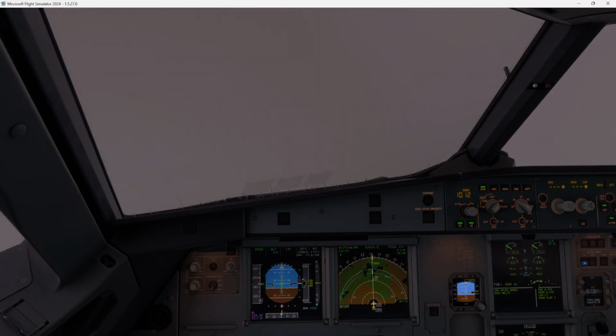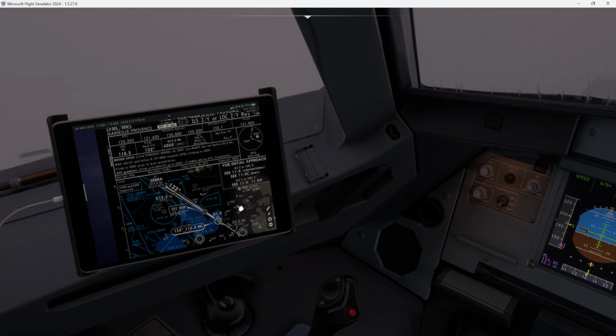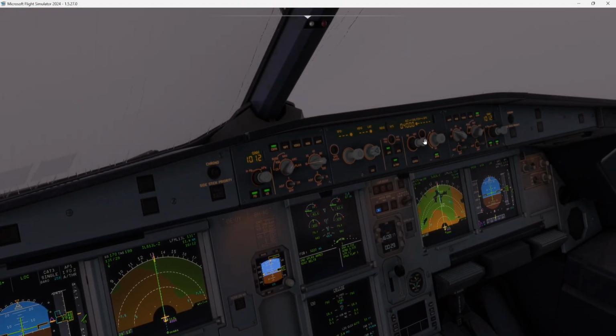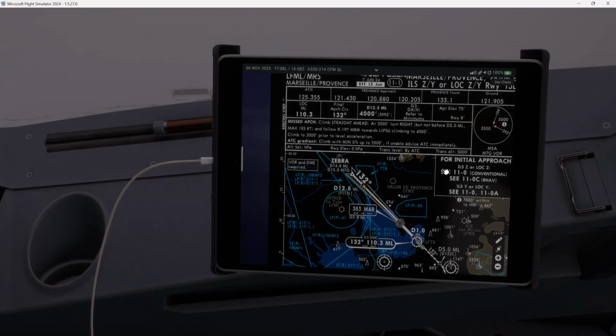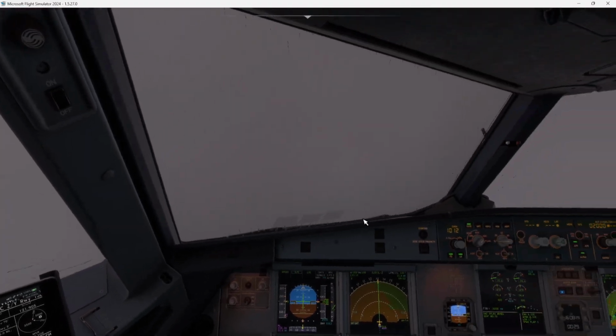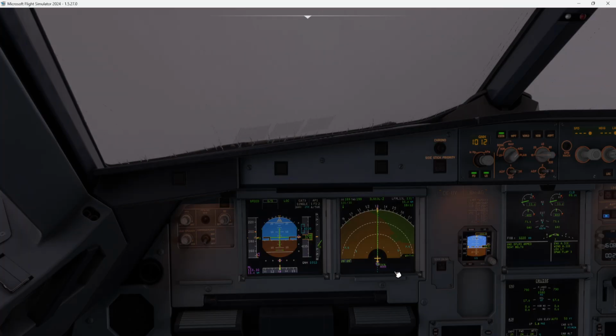Okay. Look at the green dots with the glide slope. They are matching. Glide slope star, and it goes the green dots. Now we catch the glide slope. So 10 miles. We climb until 2,000 feet. It's 4,000 actually. 2,000 no. 4,000 feet.